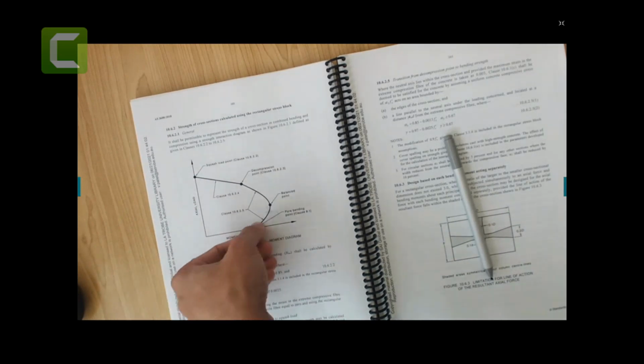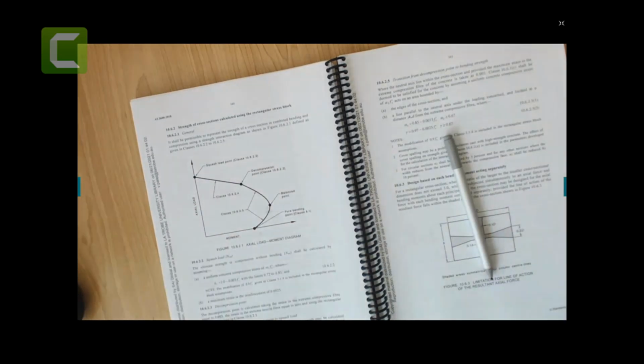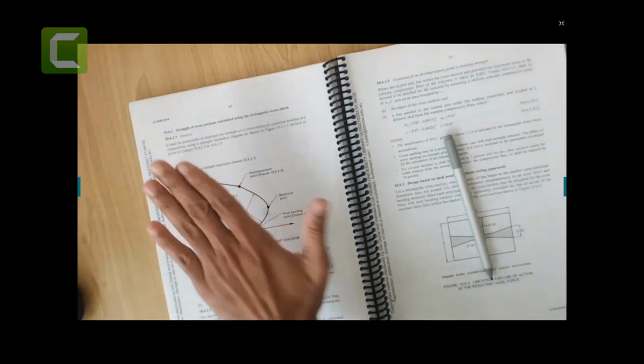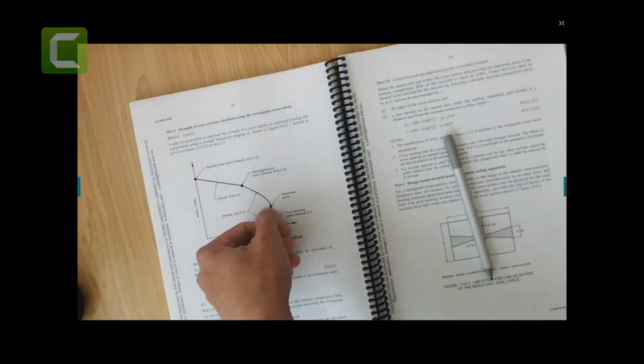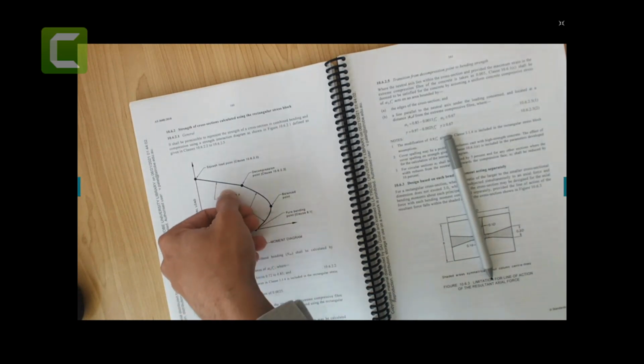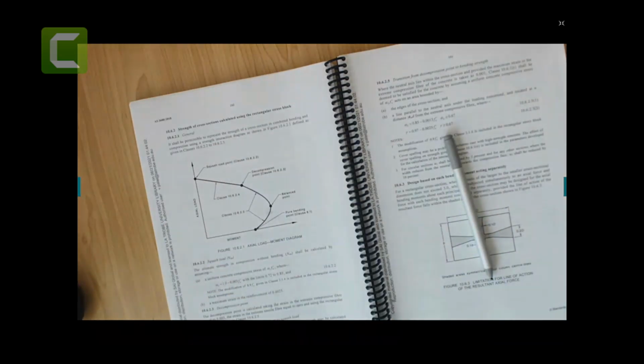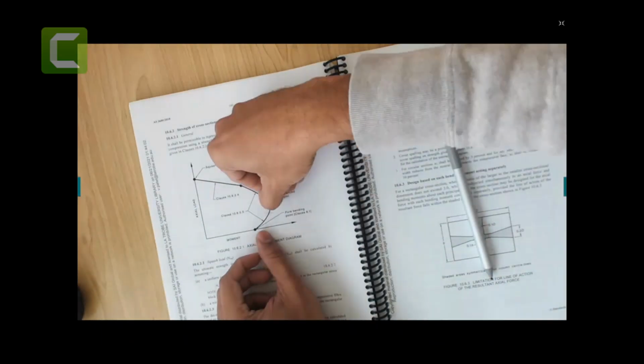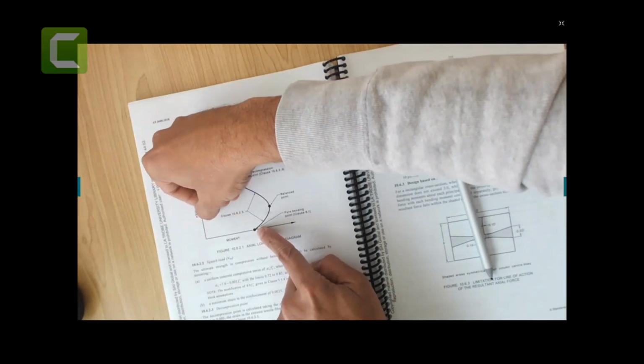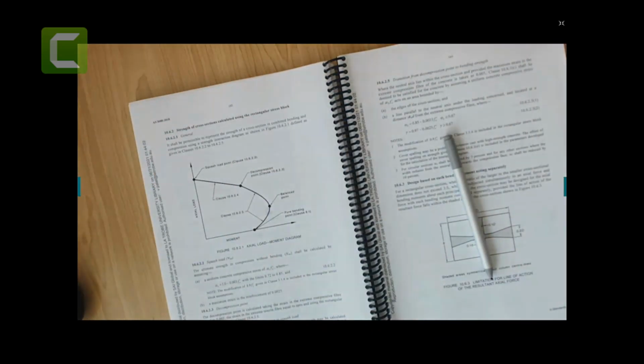If you want to have a tension one, I think it's quite simple here. If you like to get it, it's just additional information for you. So I hope you understand that. This balance point is just the one that will give you that this is the brittle failure and this is ductile failure. Brittle failure meaning that your bottom rho, which is the tensile rho, has not yielded. So from this point below, your tensile reinforcement has yielded.